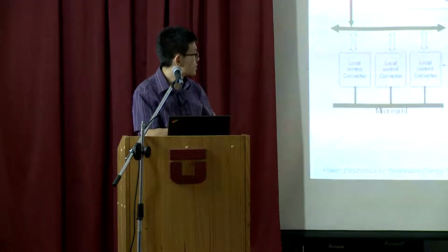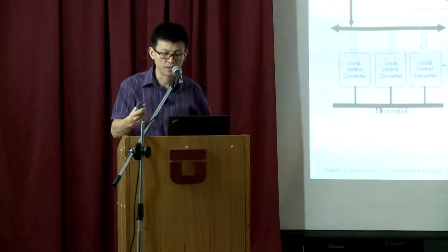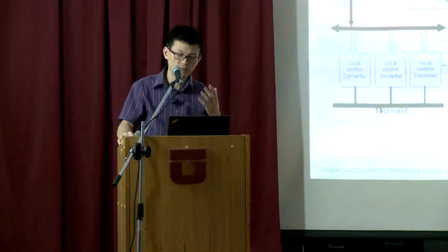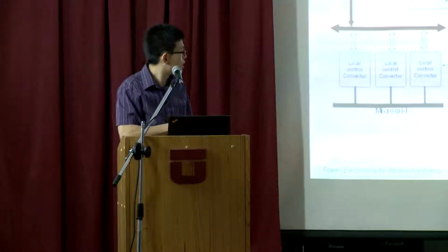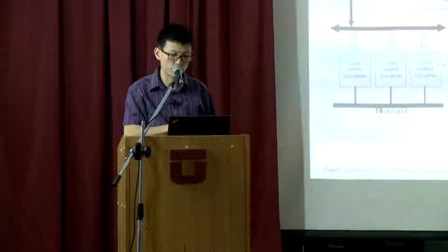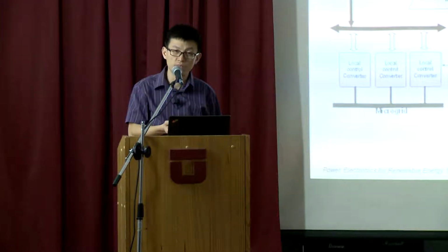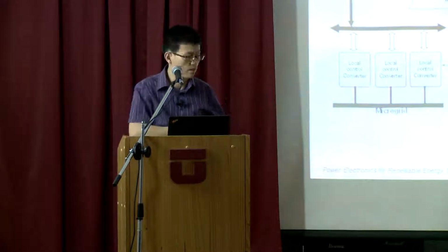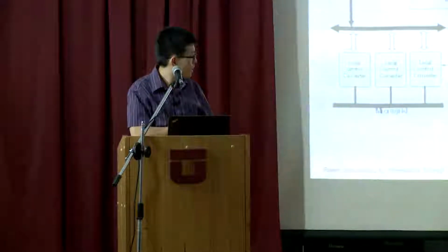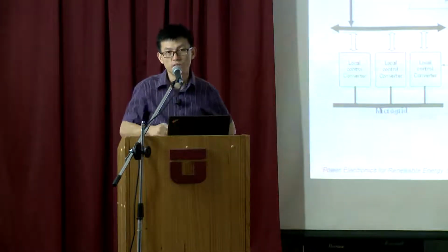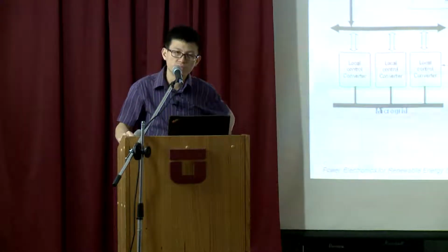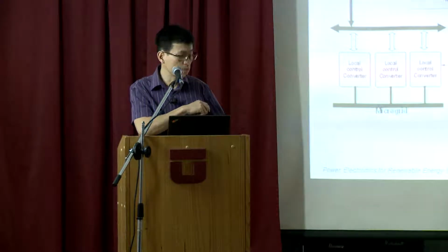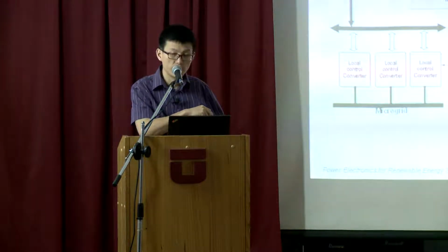Okay, and then secondary control is mainly to eliminate the DC voltage deviation caused by this primary control, due to the cable resistance or the measurement errors in the sensors. This is what the secondary control is responsible for. And then tertiary control is mainly the control between the different grids, and does the power management. So this is what we learned yesterday on the smart grid side.